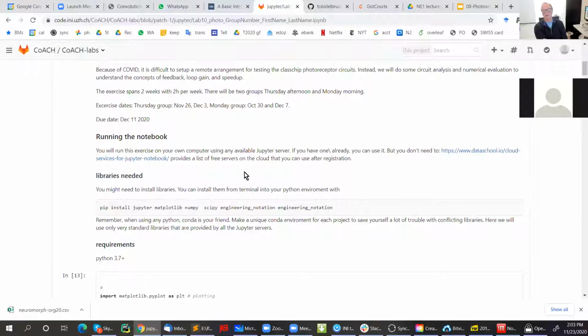In the Python notebook, I think it'll be quite fun for you because you're going to basically write your own SPICE simulation of the circuits and run this transient simulation, study how the circuit parameters affect it. And then you'll do a small signal analysis and look at the transfer functions as a function of frequency and look at the root locus plot. How do the poles of the transfer function move around as you change the circuit parameters? If you study it carefully, you'll learn a lot actually about amplifier design and the design of transimpedance circuits.